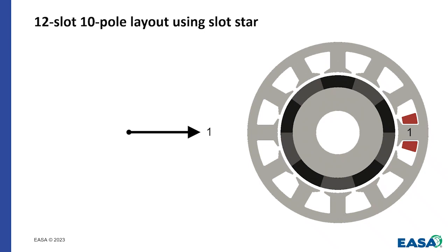But if we start by putting one coil over this tooth, and this coil you can imagine being very similar to a shunt coil in a DC field frame. So it's just quite a few turns of round copper, installed over one tooth like a field pole. If we magnetize this tooth by putting current through this coil, we could say that we'll have a magnetic field going in this direction. We're choosing the direction arbitrarily, but for slot 1, it's going to be going in this direction.